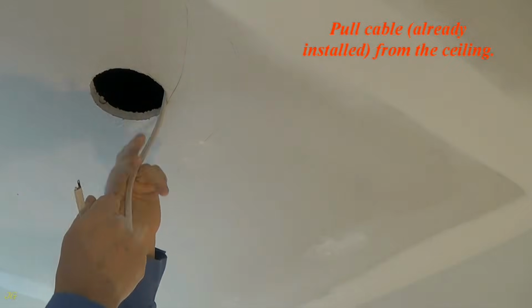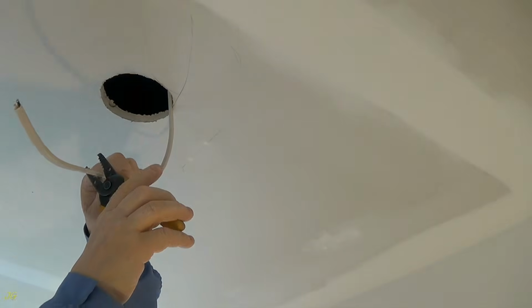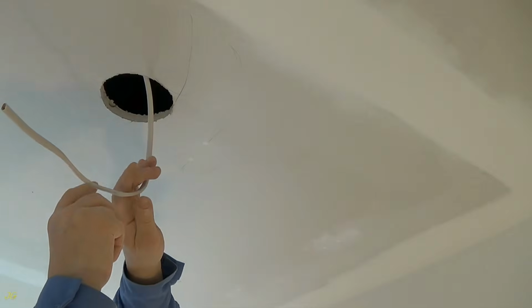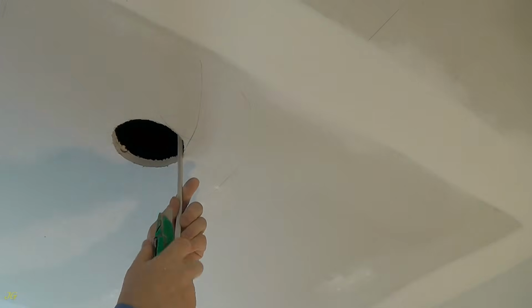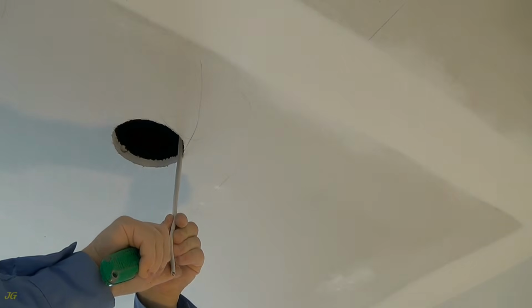Pull the cable, already installed, from the ceiling. Trim the cable if needed. Strip the cable jacket about 6 inches.